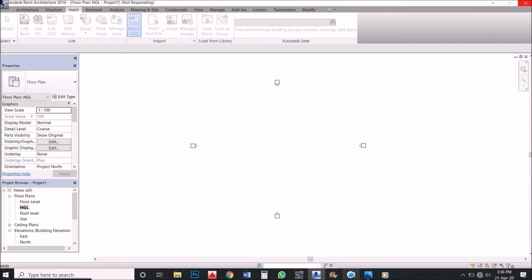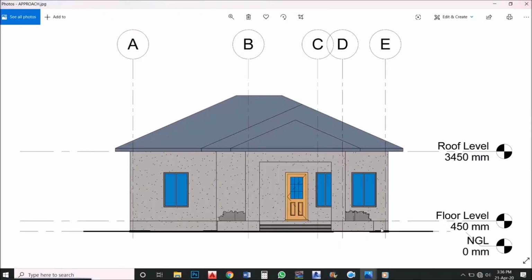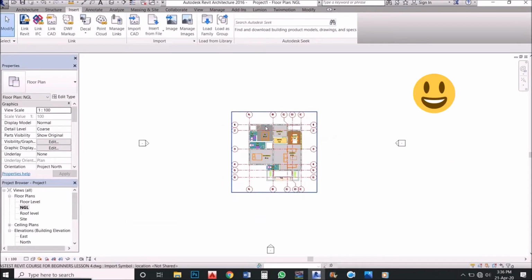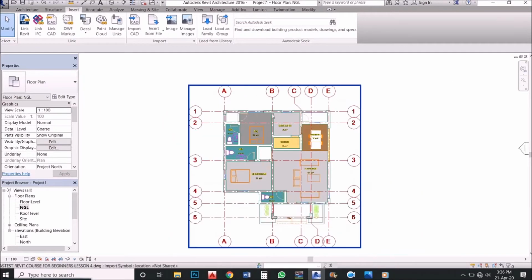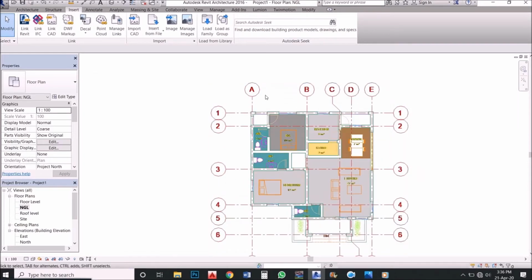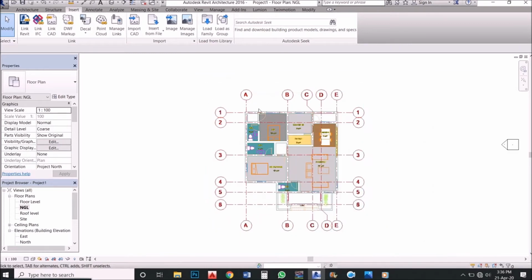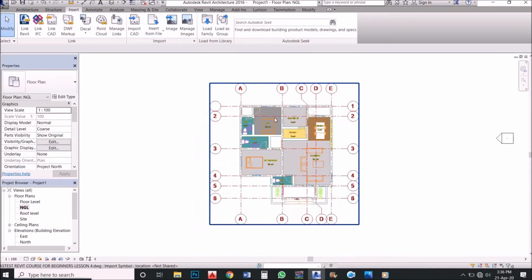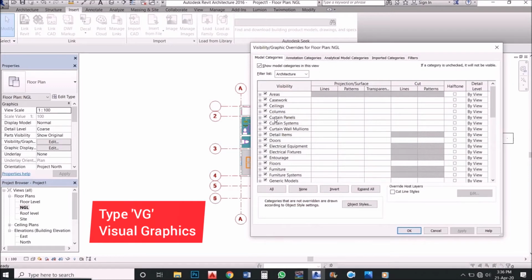So what we want to do is see how we can draw this wall to roof level in this tutorial. Okay, let's go back. The file is here. Now it's already imported into our Revit interface, centralized already, and it comes with various layers. Now if we want to make this a bit little, see it's a bit shouty, different colors here and there, we want to make it faint, so you click on VG, Visibility Graphics, the shortcut, VG on your keyboard.